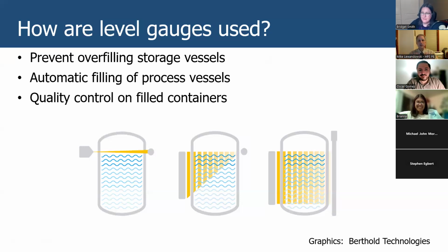And that gives us a little better way to measure the level of the material. Instead of just saying it's full or it's not full, now using a line source and a point detector, we can get some feeling for how full this container is. And if we want the best measurement, we have both a line source and a linear detector. So line source and line detector, I haven't even done the math, but I'm sure it's scary. But that gives us the best way of figuring out at what level the container is filled.